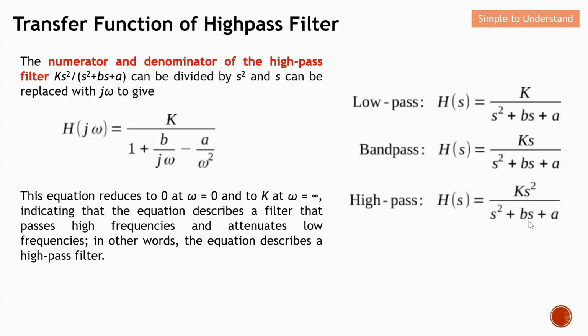Okay, so b divided by s squared, I will have this s term over here. And basically this a divided by s squared, the j squared will become minus here. So this is actually another way to describe the equation. Now, this w equals infinite, which means that this is infinite, and this is also infinite. From here, you can see that infinite number minus infinite number, I will replace this whole thing with 0. Therefore, my transfer function will be equal to a.